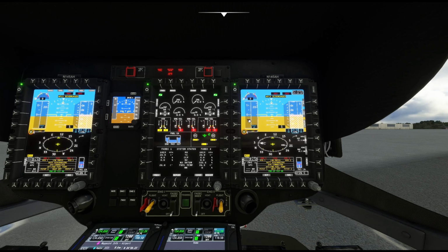All right, T1 is on the engine intakes. Collective lever position is this guy right here. So it's basically saying that the FADECs are receiving this collective lever position from the aircraft, and then we just make sure that that matches. And it looks like it does. All right, this is our actual N2 being reported by each of the engines. This N2 datum is the N2 that Helionics is sending back to the engine, saying this is where I want the rotor to be. And then our current fuel temperature, so the fuel flow meters are also temperature sensors, and that's where you're going to get this from.